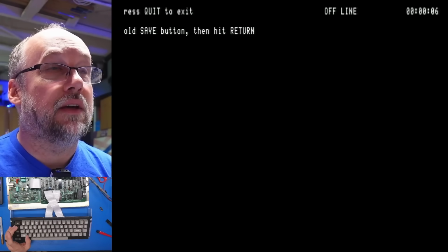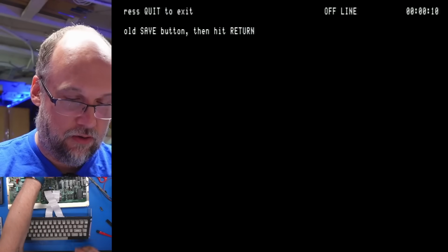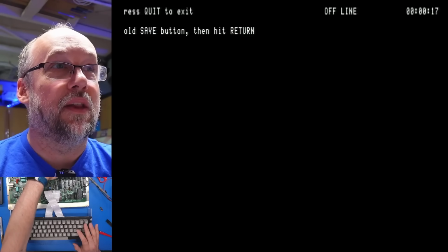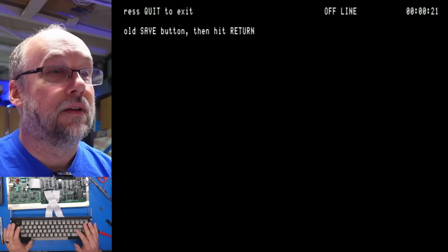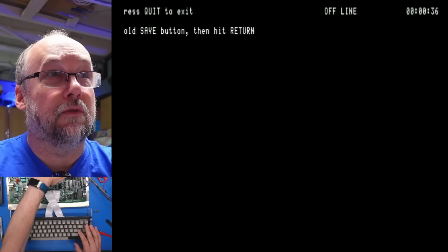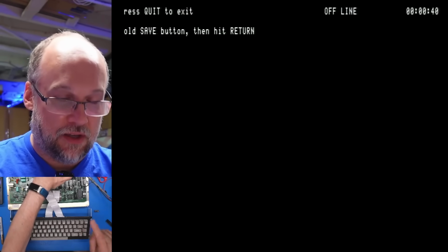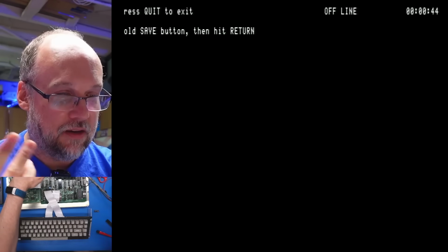Okay, well, it seems to have lost its content. Hold save and hit return. I'm going to do that. It seems to want me to do that to get out of here. Ah, without the chip in there, it's not even able to exit this. And let's see if I hit quit to get out of here. No. Holding save and hitting return, that no longer works. It worked when this chip was in there, but I guess it tries to save the contents and read it back. And if it's not able to read it back, then it just gives up.